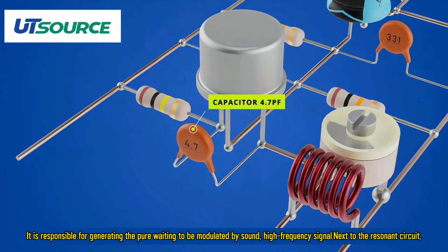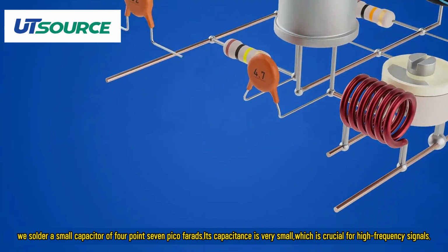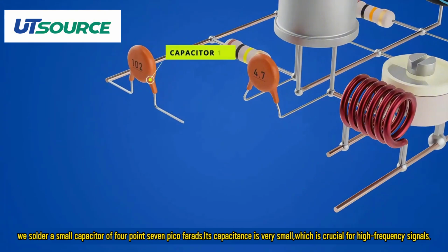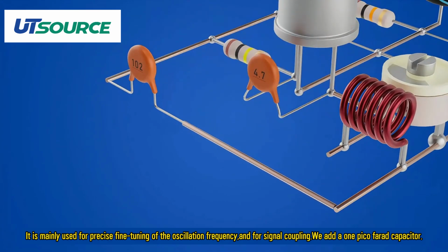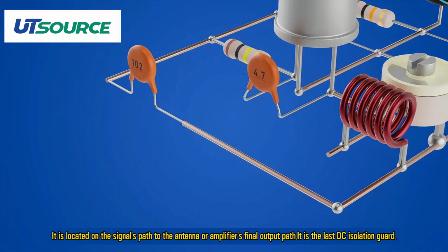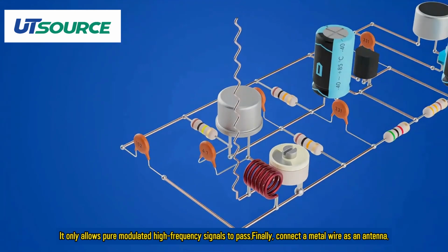Next to the resonance circuit, we solder a small capacitor of 4.7 picofarads. Its capacitance is very small, which is crucial for high-frequency signals. It is mainly used for precise fine-tuning of the oscillation frequency. For signal coupling, we add a 1 picofarad capacitor. It is located on the signal's path to the antenna or amplifier's final output path. It is the last DC isolation guard. It only allows pure modulated high-frequency signals to pass.